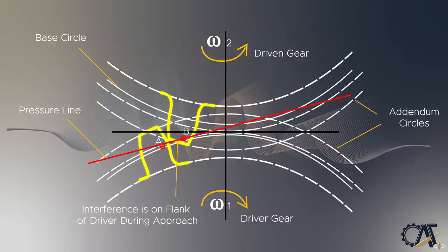It is important to note that if the gear is positioned at the center of the graph, the angle between the horizontal black line and the red line is the pressure angle. A common value of 14.5 degrees was historically used in diametral pitch gearing. The basis for this selection was that this pressure angle allows for reduced noise in the gear mesh and exhibits a lower rate of wear.